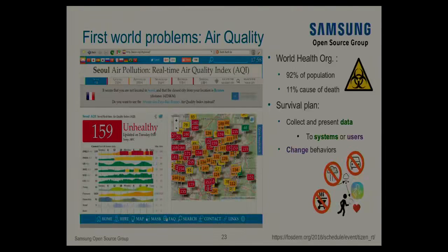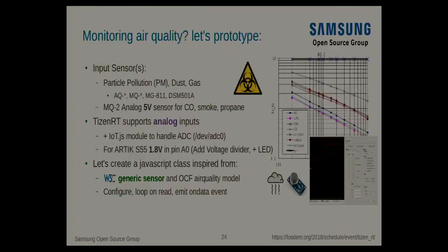The first thing we have to do is to get to know where we are and how we can proceed. I have been working on a sensor, just trying to measure the quality of the air, and when I got this result I can try to establish a scenario. To create the demonstration I've been using an analog sensor. You have to be careful because those sensors work at 5 volts. My board is working at 1.8 volts, so you have to make a level shifter and so on.